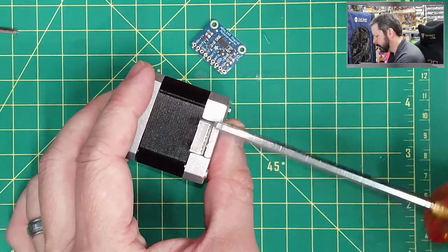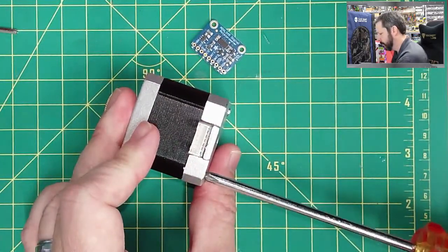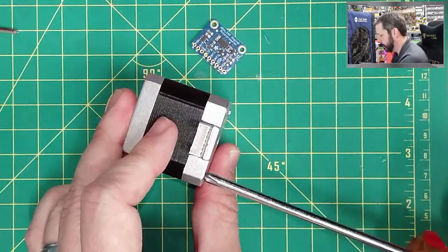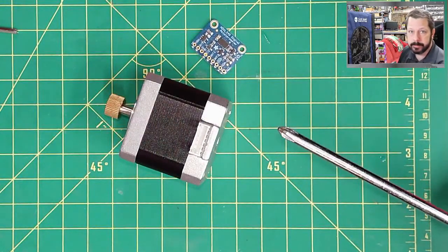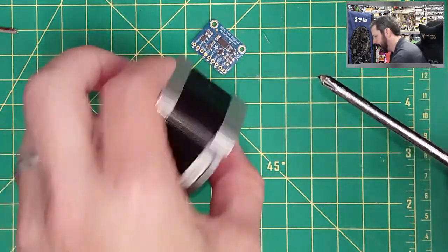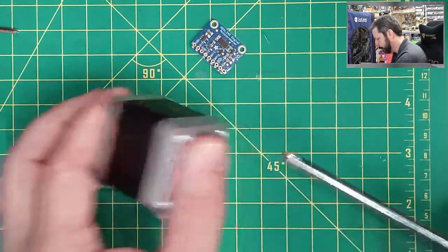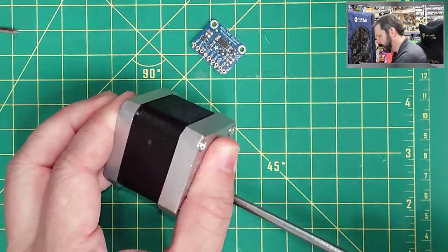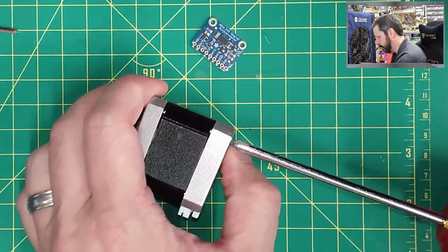It might be that the cable is not matching up with how this thing is wired internally, and the board that is running the code to send the commands to the stepper motor. So I have occasionally, not very often, had to switch wires around here on the cable.